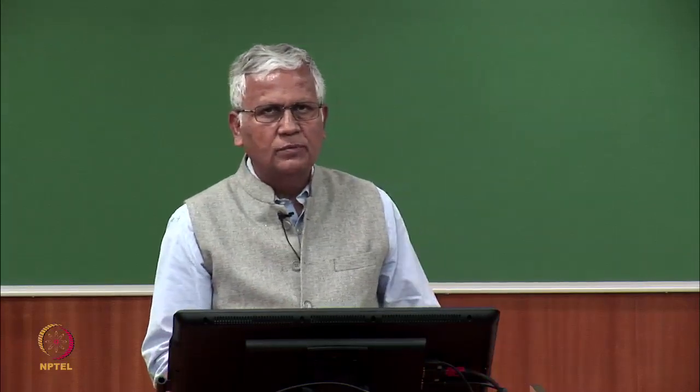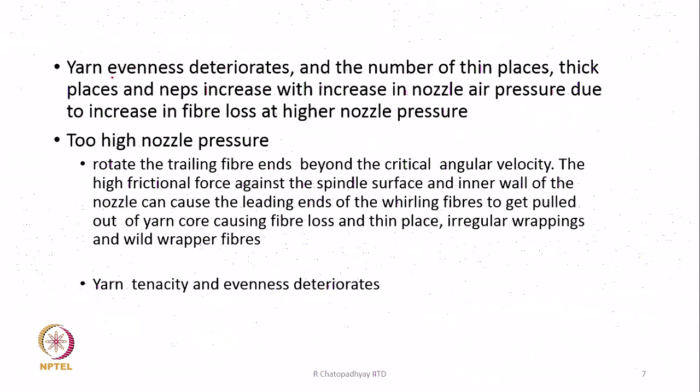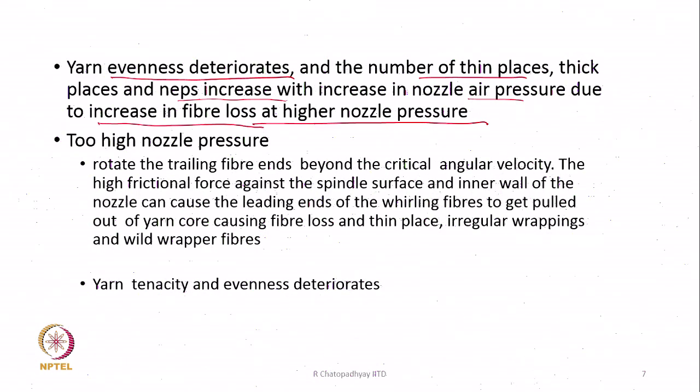But with nozzle pressure increase, yarn evenness may deteriorate. The number of thin places, thick places and naps may increase because of the increase in fiber loss at high nozzle pressure. This is also something you have to remember: loss of fibers is going to increase at higher nozzle pressures, and if there is loss, there is a chance that more thin places will develop.